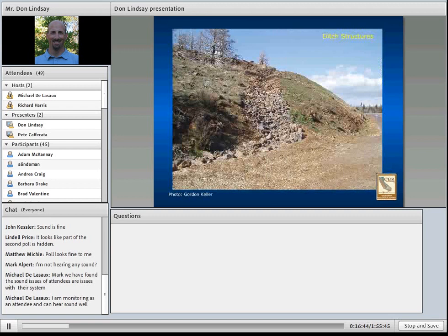Another type of ditch structure is an intercept or catchwater ditch positioned upslope of cut banks. Although not too common on low-volume roads, intercept ditches are used to collect and redirect runoff before it can flow over oversteepened cut banks that are prone to erosion. They are best suited in extremely wet climates where sheet flow is common. Due to their steep gradients, they are often required to have some sort of scour protection, which we'll address later.